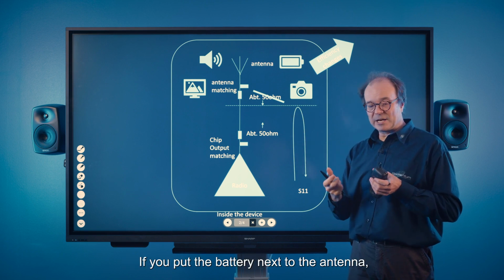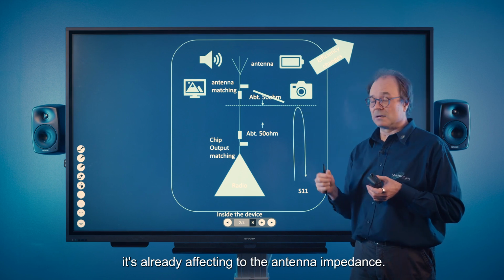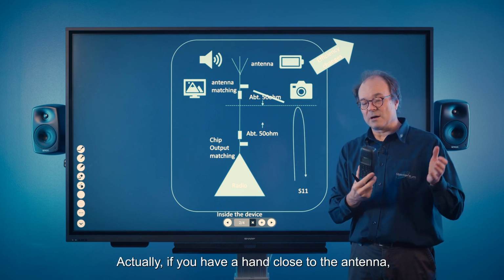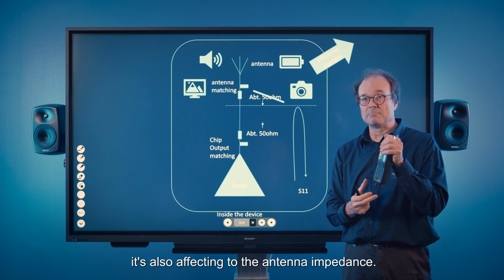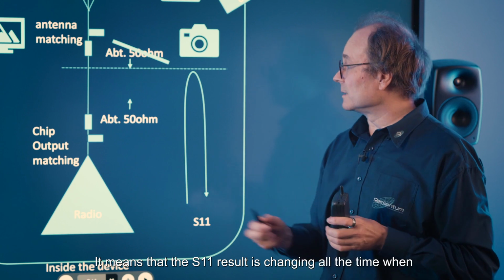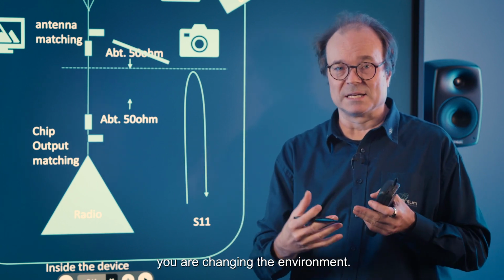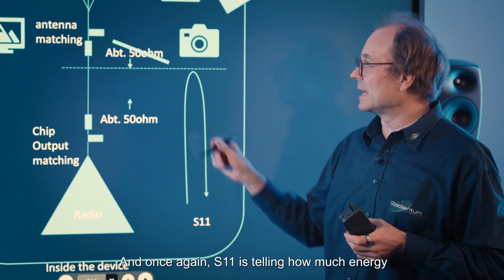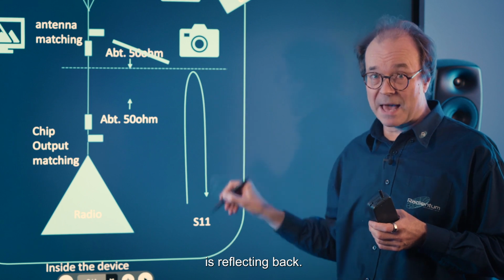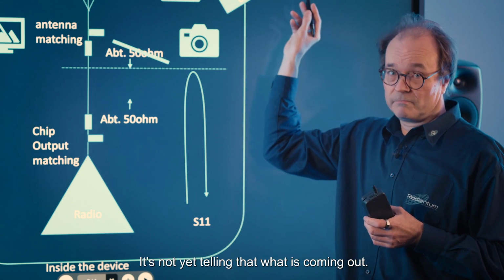If you put the battery next to the antenna, it's already affecting the antenna impedance. If you have a hand close to the antenna, it's also affecting the antenna impedance. It means that the S11 result is changing all the time when you change the environment. And once again, S11 is telling how much energy is reflecting back. It's not yet telling what is coming out.